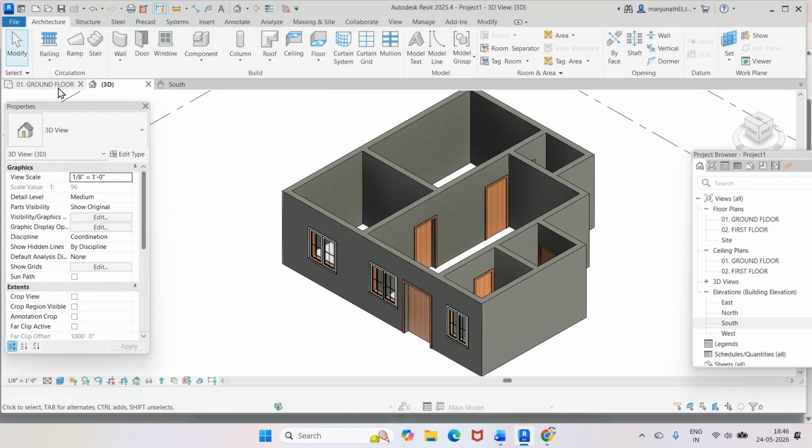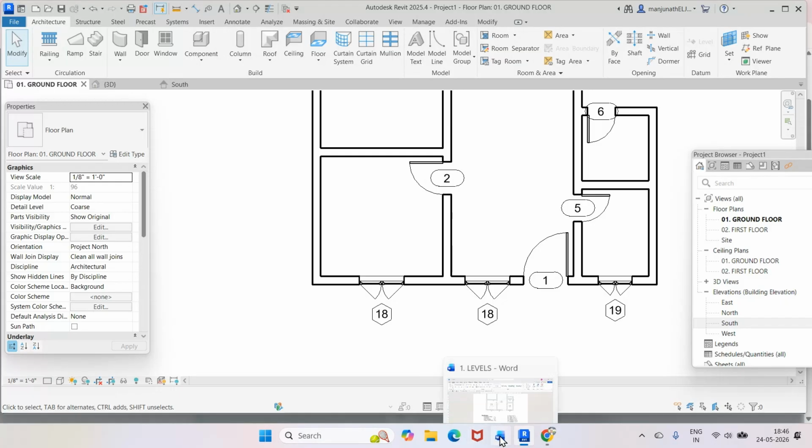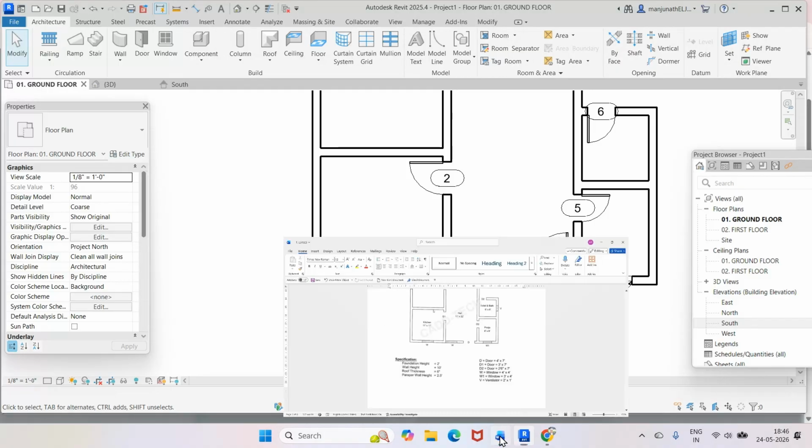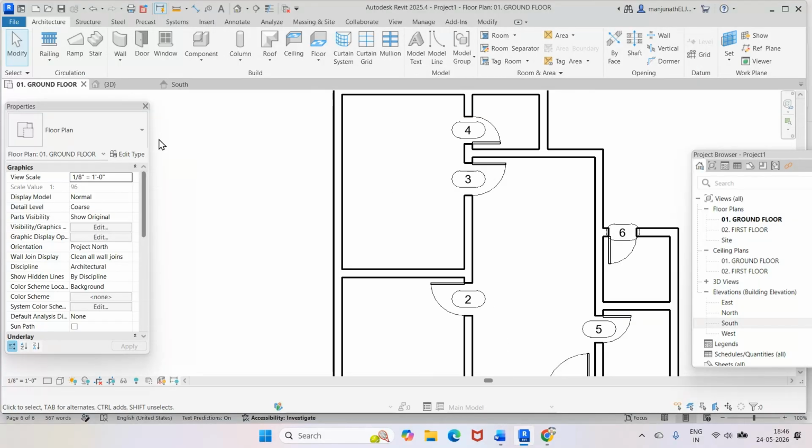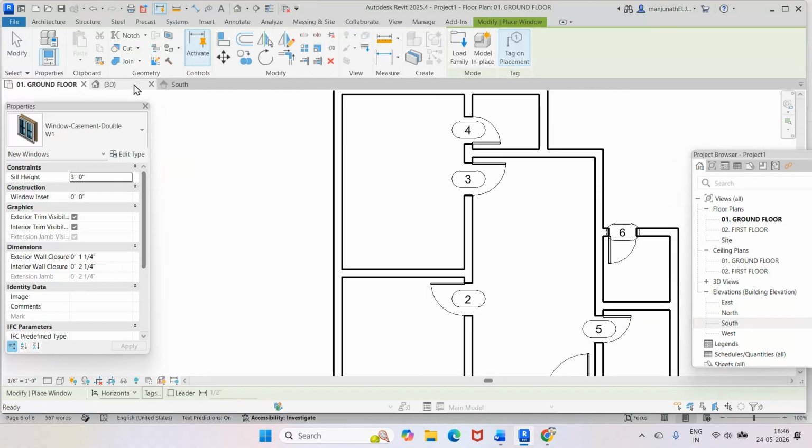So after that, now I want to go for here. There is no window here in the kitchen in this one. And I want in the bedroom, I want W1 here. So here I will just go to this window, then go to Windows. W1 is this. I will take it on this side. So I will take exactly at the center. So you click on this side and say escape. So we have this window here. Then after that, in all other cases, we don't have anything else now.